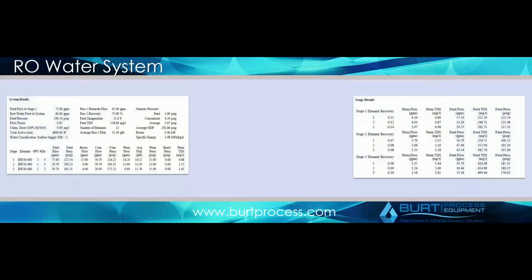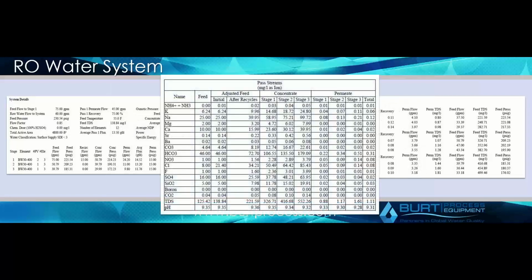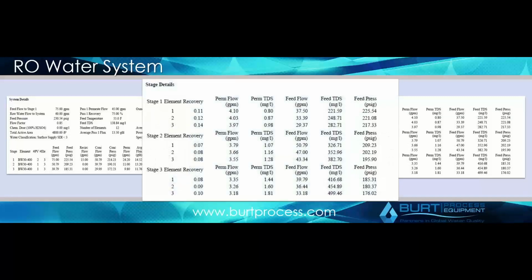Okay. So again, this is the RO projection from before, which was shown earlier. This is the RO. Obviously, we talked about this in great detail, whereby we're going to do 98% of the work in our system to achieve our water quality targets. Again, low TOC, very, very high resistivity values. The projection here is a 2x2x1 array.